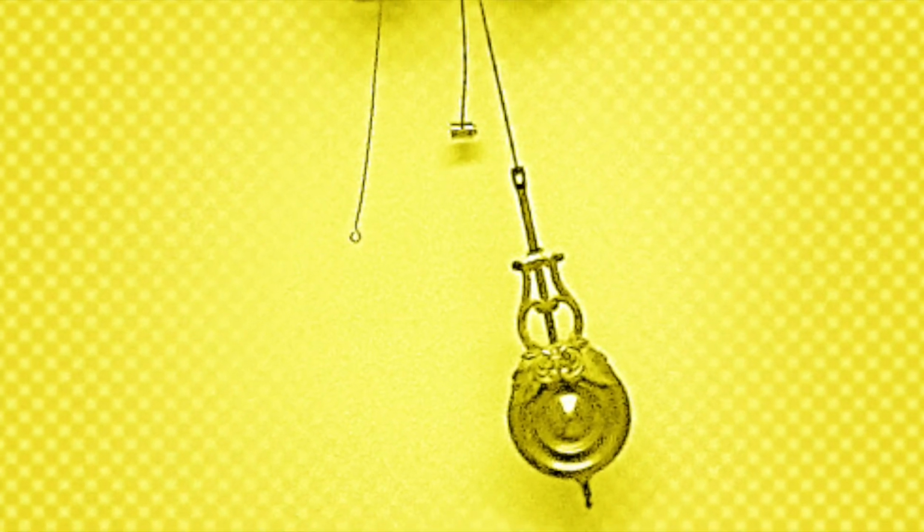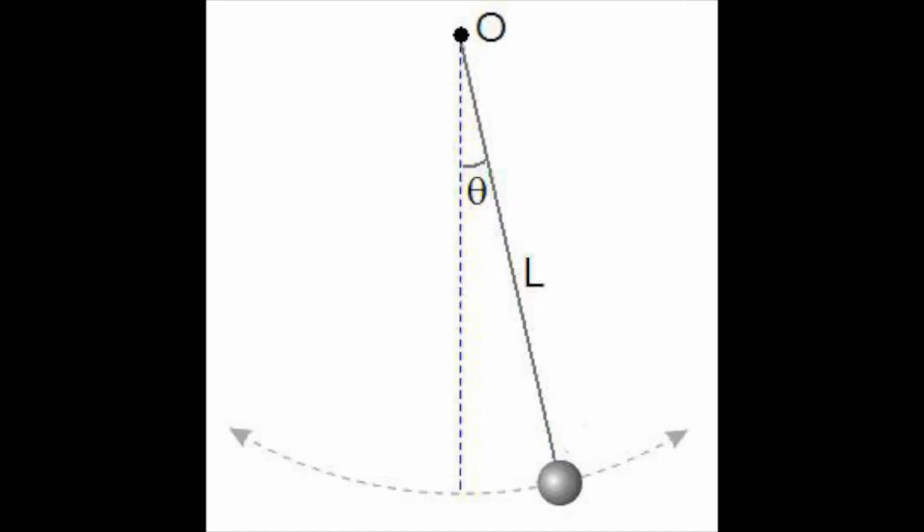To simulate the motion of the pendulum, we will determine the forces acting on the pendulum bob and use numerical integration in order to compute the changing velocity and position of the pendulum across very small time steps, effectively simulating the behavior of the pendulum mass. The simulation is written as a MATLAB script and can be found in the supplementary files.